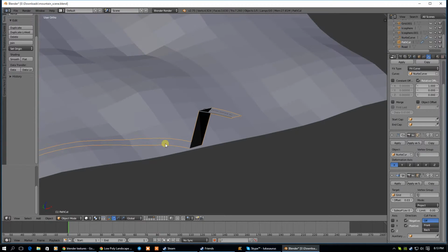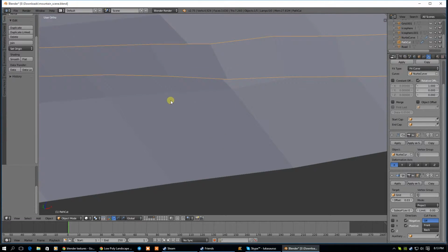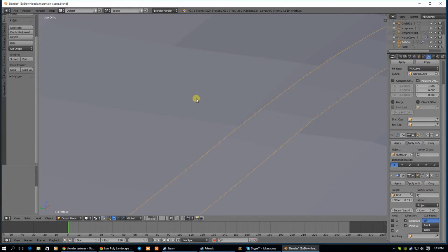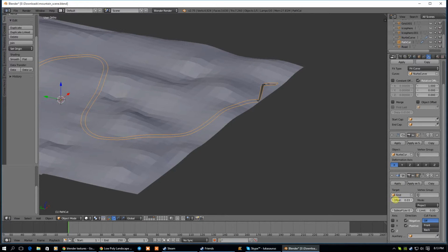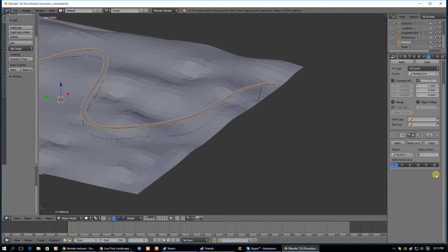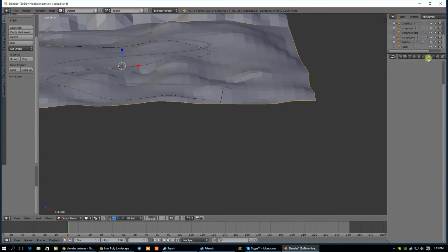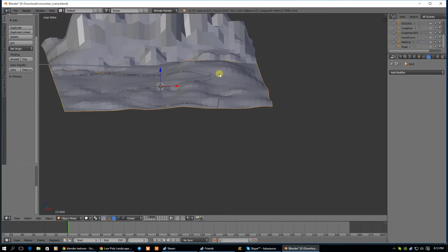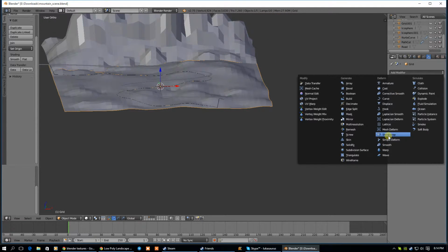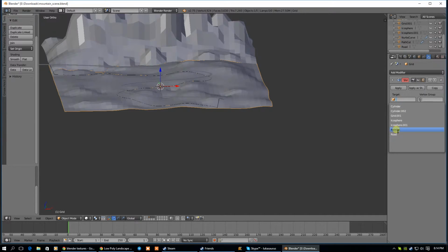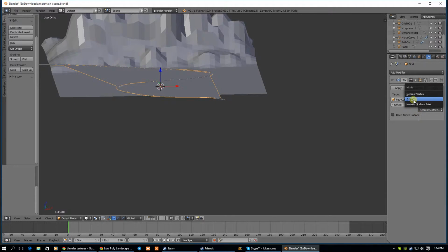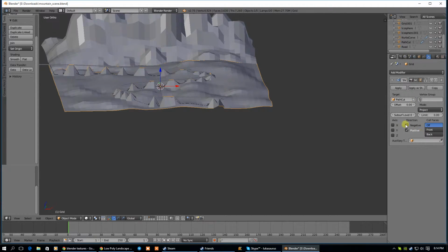should have those edges on it. If I go down to this here, it doesn't seem to have them on it. So I might see. No, okay, I'll remove that from there for now. What I'm going to do is click on this and add a modifier to this. This is the mesh here. I'm going to add a shrink wrap modifier to this, and I'm going to target the path cut. It's going to be project, and it's going to be negative and z-axis.